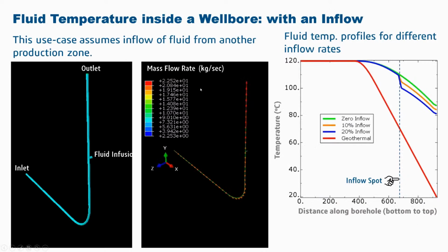In a similar example, we can also model the temperature of a fluid inside a wellbore with an inflow. So if you have multiple sources of fluid, how those inflows affect the temperature can also be simulated and captured through this kind of simulation. So here we have a borehole system with fluid infusion, and we are able to track the temperature of the fluid throughout the borehole for different inflow rates.